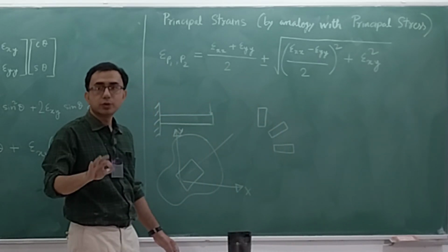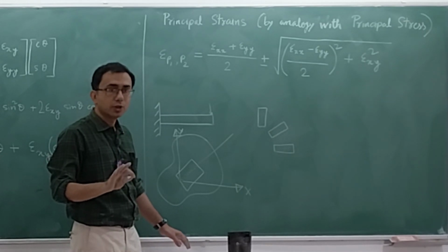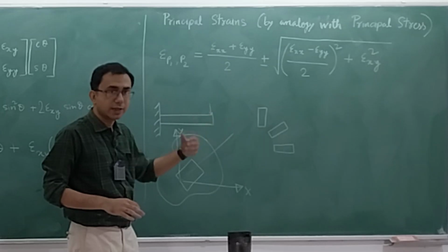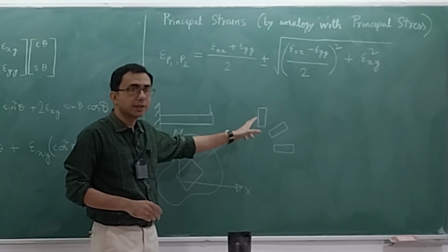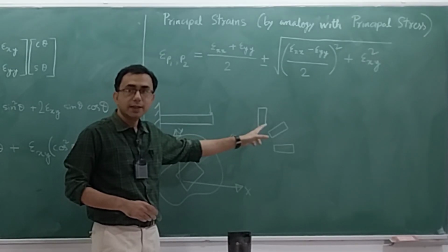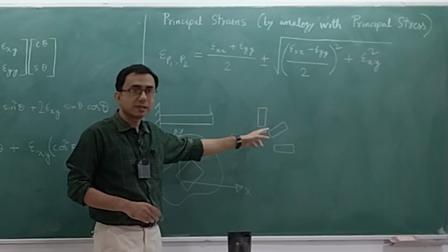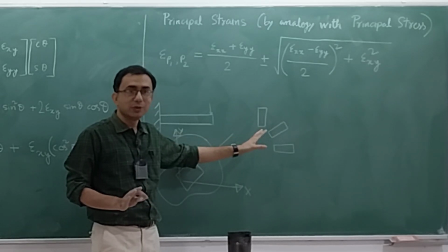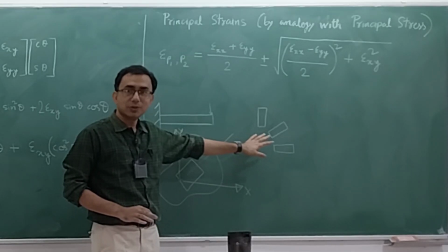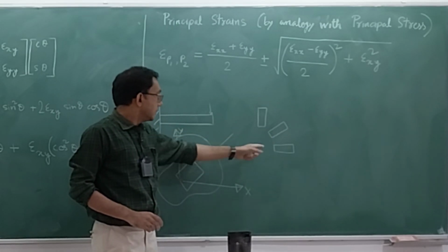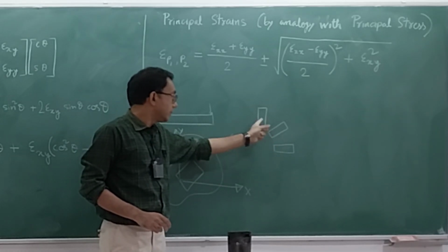And you do not have to take the trouble that you will buy 3 strain gauges and then go about sticking all of these things in this particular combination and then worry whether it is 45 degrees or 46 degrees. You don't have to worry. You can actually buy strain gauge which comes in a nice combination. This is 0, 45, 90.